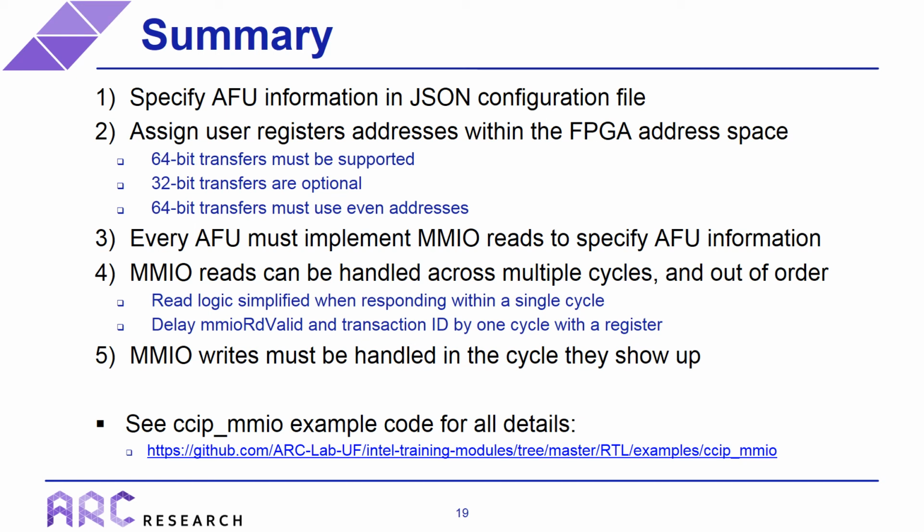MMIO writes are a little bit easier. MMIO writes have to be handled in the cycle that they show up on CCI-P, otherwise the data will be lost. And just a quick reminder, all of the code that I used for this example can be found in the repository shown at the bottom of the slide. It also includes how software communicates with this and probably has a lot more comments than I was able to include in these slides, so I'd recommend that everybody check that out.